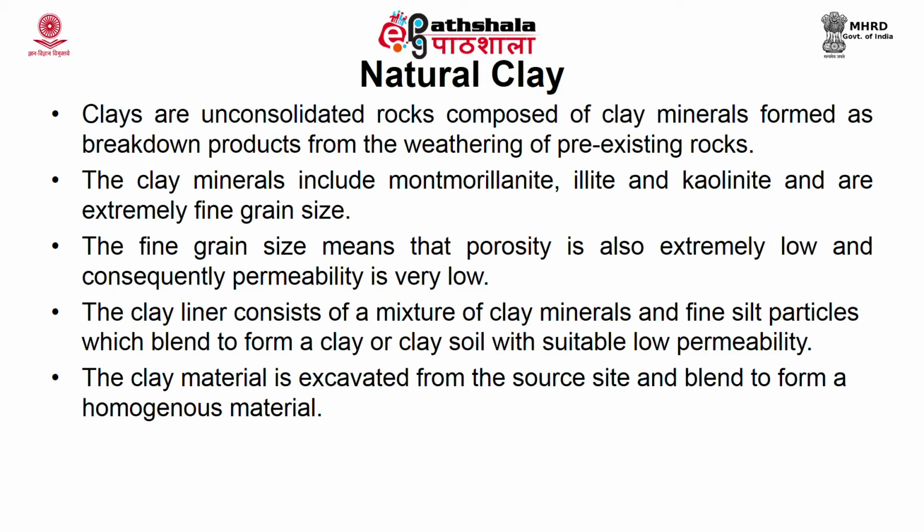The clay material is excavated from the source site and blended to form a homogeneous material. Blending will be done by mixing clay minerals and fine silt, so that you get a clay soil. And I told you that the permeability of this material will be very low.